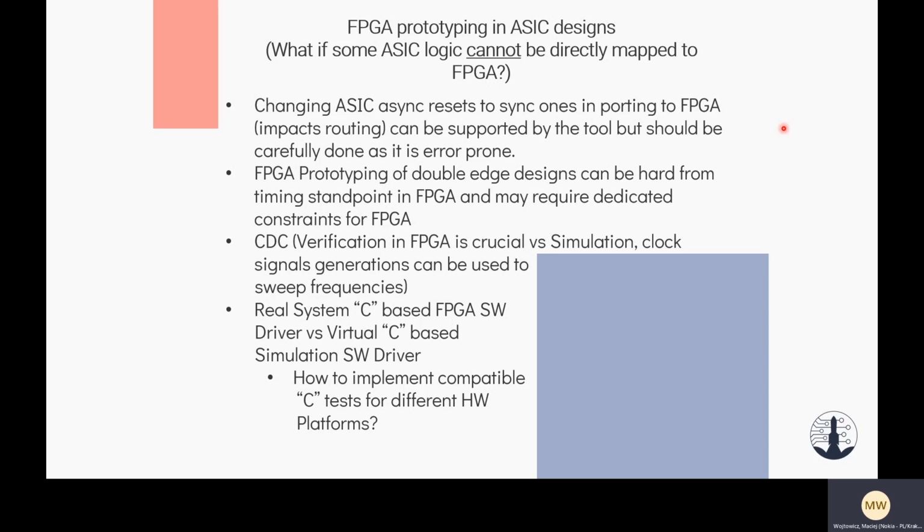Returning back to writing tests in C, the good thing is that for ASIC verification and FPGA verification, we can build a real system transaction layer and use the same piece of software to verify the ASIC in simulation and in FPGA. Of course, some parameters in our C environment can be FPGA board specific, but it is possible to port the tests, and with one software driver we can verify our design both in FPGA and in functional simulation.